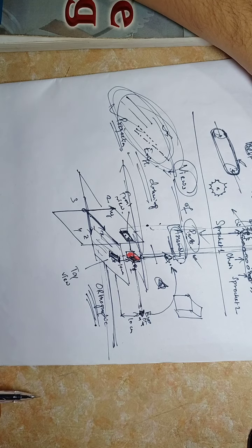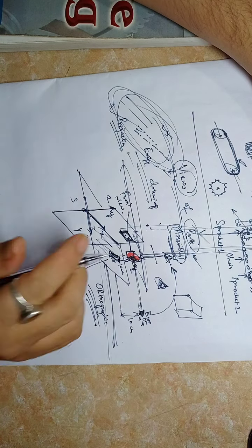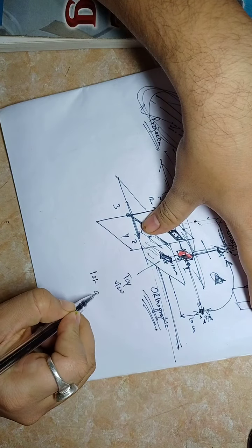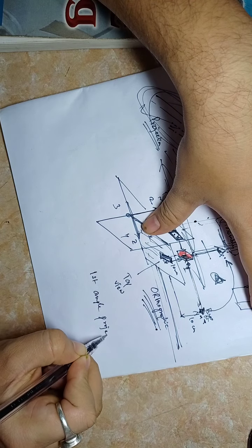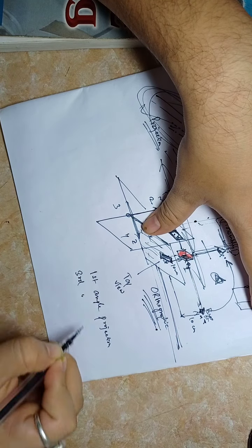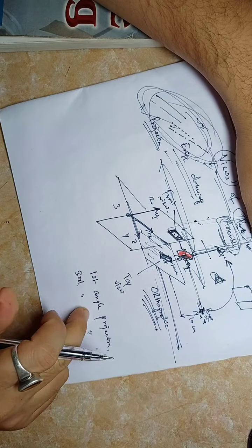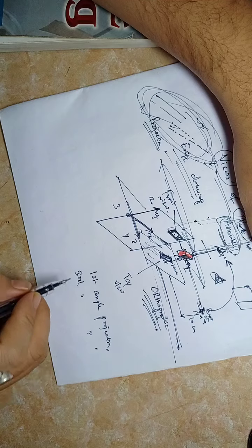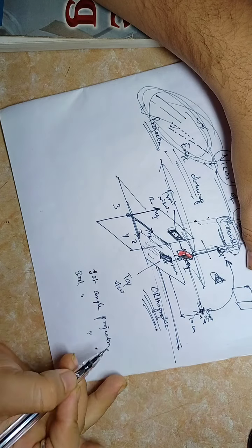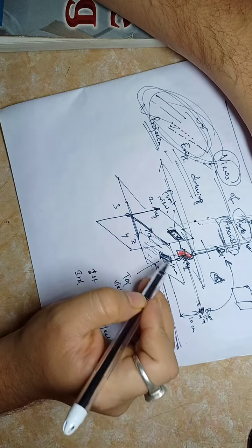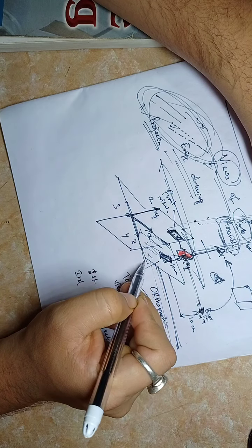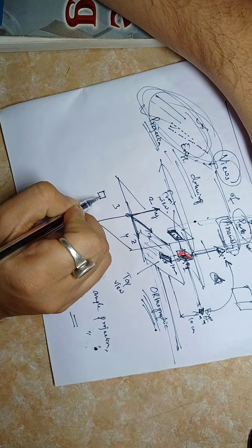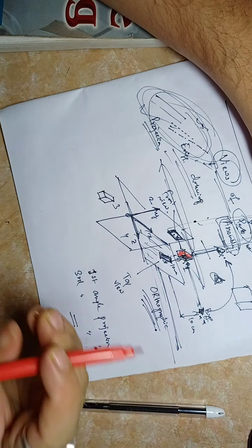Okay, fine. One thing that you have heard about is first angle projection and third angle projection, because these things are also basics and you have learned them in your engineering drawing. First angle projections are obtained when you place your object in the first quadrant, and third angle projections are obtained when you place the same object in your third quadrant, right here, let's say.